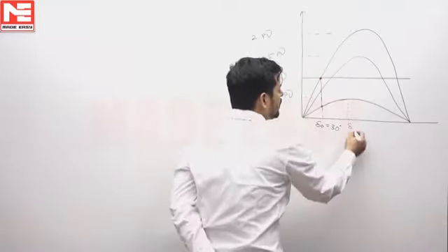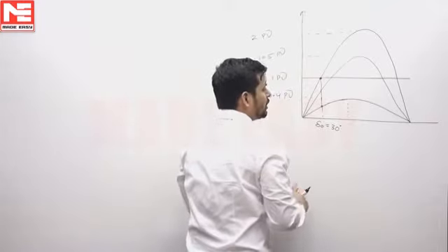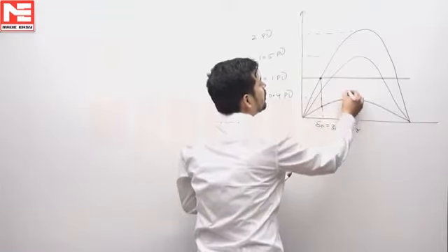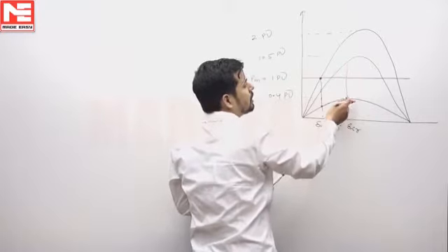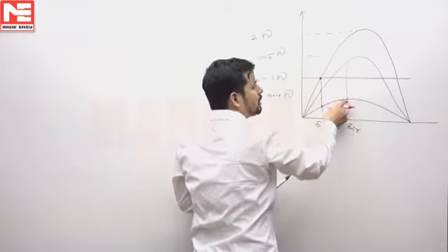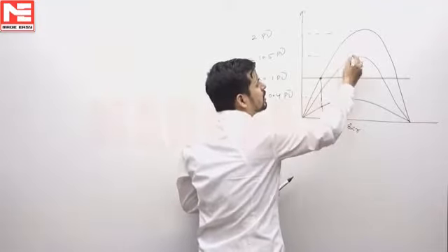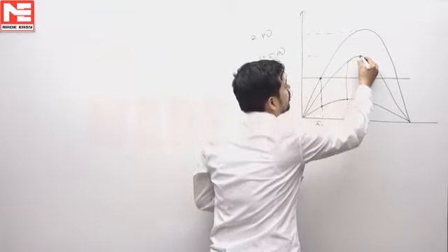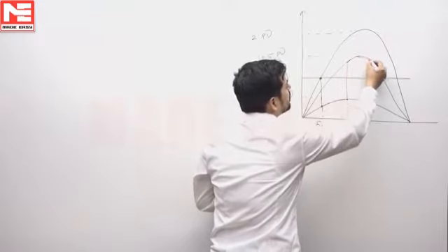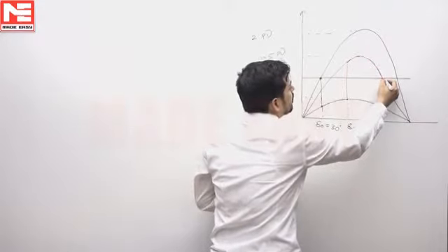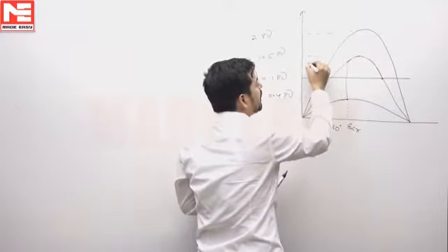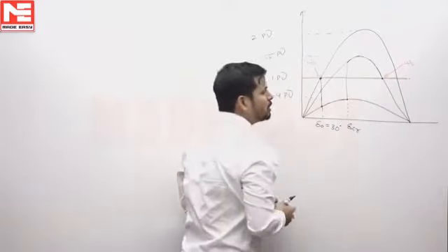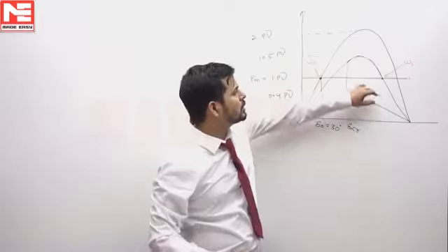So, we will assume that we have cleared the fault in a critical condition, so that after clearing the fault, the operating point shifts to the post fault condition, and after that the machine decelerates to find the synchronous speed once again at this critical point. So, the machine has synchronous speed at this point and synchronous speed at this point. So, corresponding to the critical clearing, the machine will attain synchronous speed at this critical point.